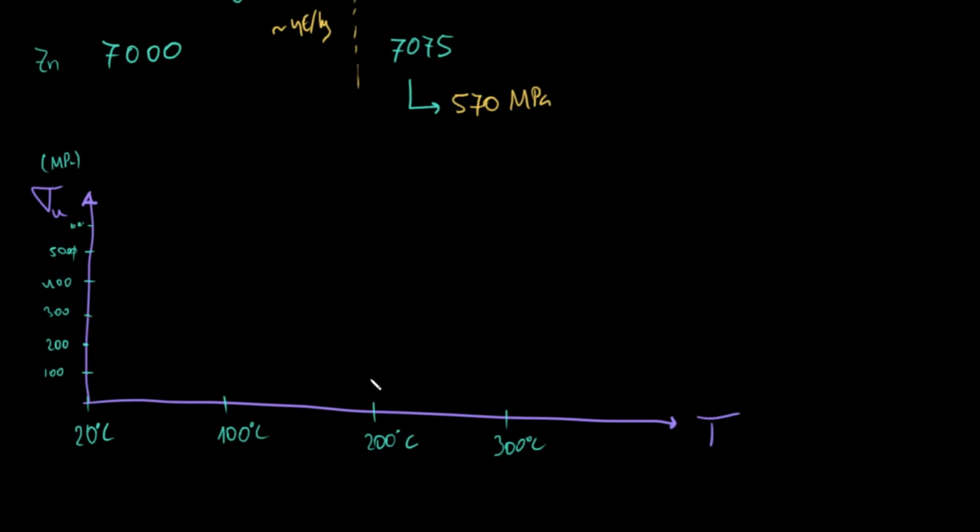Then at 200 degrees, maybe it's already at 100 megapascals. Then at around 250 degrees centigrade, it's going to be maybe around 50 megapascals. This is nothing.